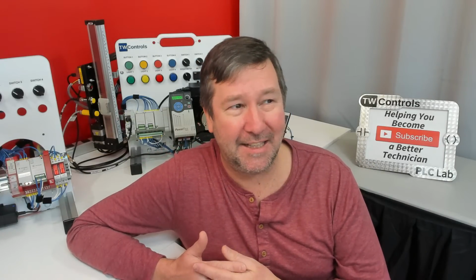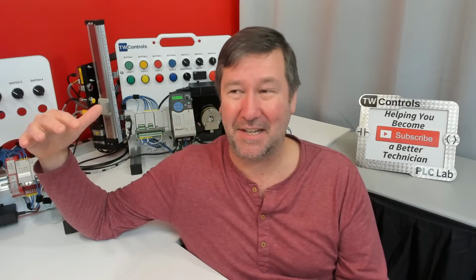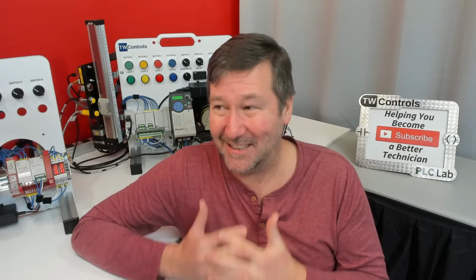We talked a little bit about the difference between ladder logic and function block. What I always tell people is it's very regional. If you're in the U.S., especially with anything built up around our traditional industries, it's going to be ladder logic, and it did stem from the replacement of relays. I don't like to get too much into the history of PLCs, but if you're getting equipment from Europe, they really didn't grow up the same way. So with European equipment you'll see a lot of function block diagrams; in the US, a lot of ladder logic. You need to be versed in both of them, is what I always tell everybody. Everybody always wants to know which one's better. Neither.